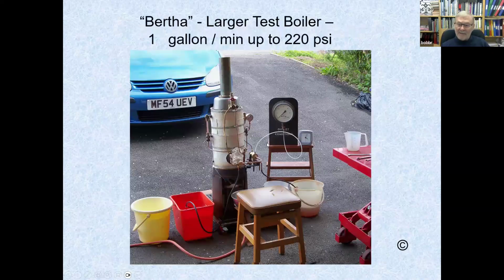And this is my test rig. And I made some quite big injectors for traction engines at one time, but they were uneconomic for me to make with a centre lathe. You really need all the CNC to do it properly and make a profit out of it, so I packed in doing them. But there's this special valve you can see, and you can measure the output pressure, you can measure the boiler pressure, and you need a clock to time how long it's going so that you can work out the flow rate. And it was gas fired, very simple.